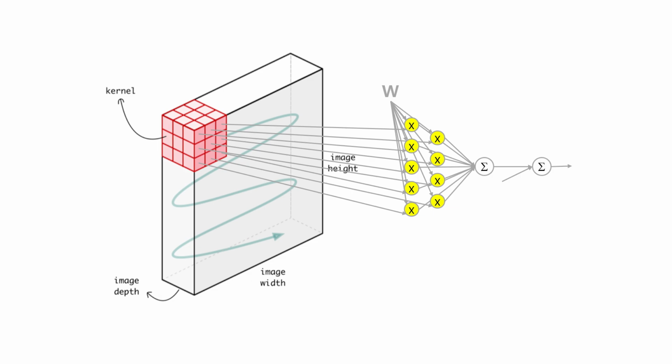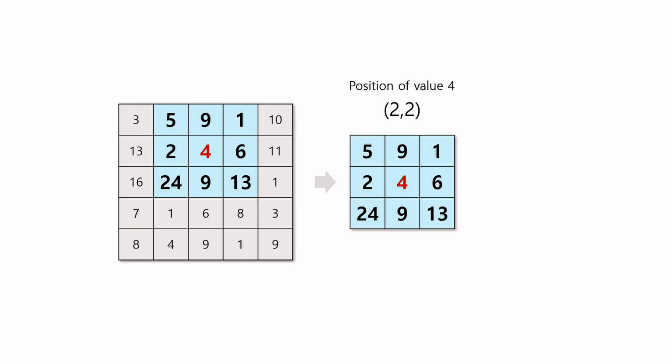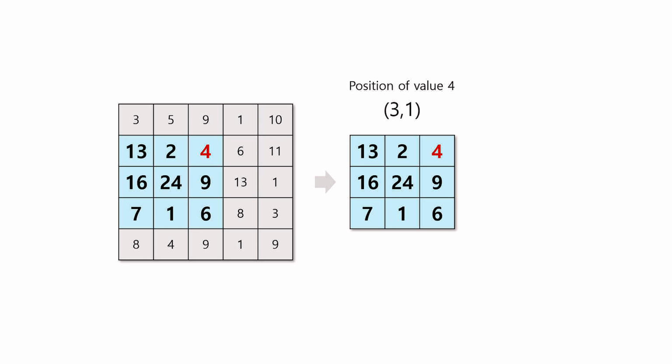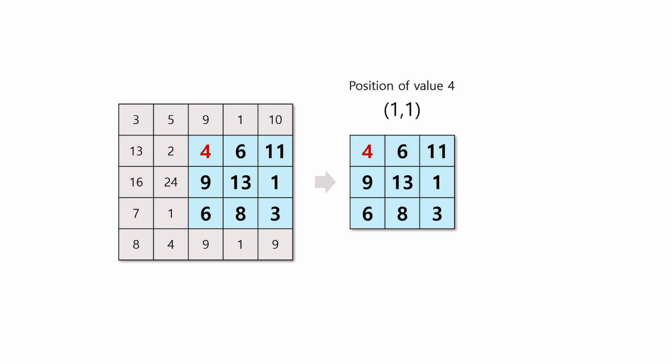Since K by K data must be read simultaneously for each clock cycle, we can think of a method to store them in different memories and read them simultaneously. But data items of a specific feature map cannot be fixed in one memory because their locations within the receptive field move for each clock cycle.